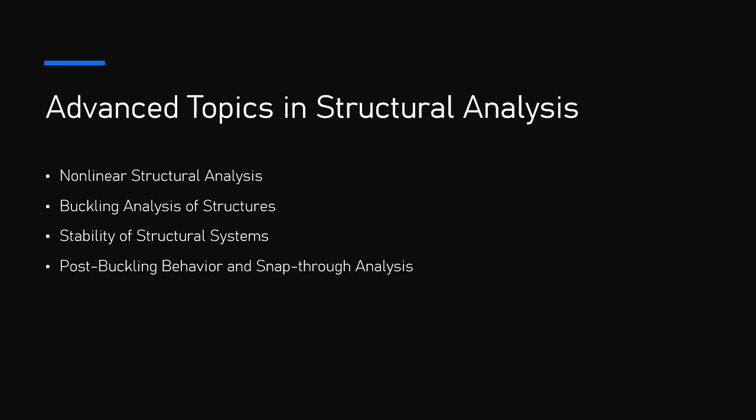2. Plate and shell design. Plates and shells, particularly thin-walled members, must be designed to prevent local buckling. Reinforcements such as stiffeners or ribs may be added to increase the critical buckling load of a structure. 3. Bracing and lateral support. To prevent lateral torsional buckling, beams and other structural elements are often braced or restrained to maintain their stability during loading. Braces help reduce the effective length of the beam and increase its buckling resistance.